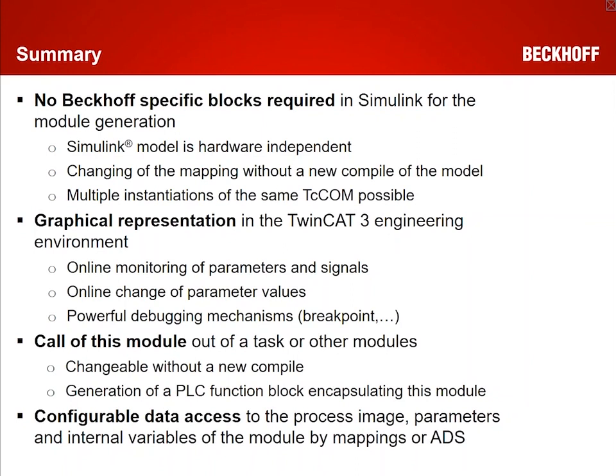You can also change this without a new compile. So if the MATLAB engineer decided this module should be called out of a module, you can afterwards just say, I don't want to use it out of the PLC or C++. I want to set it into a task context. This can be changed afterwards in the instantiation of the object.